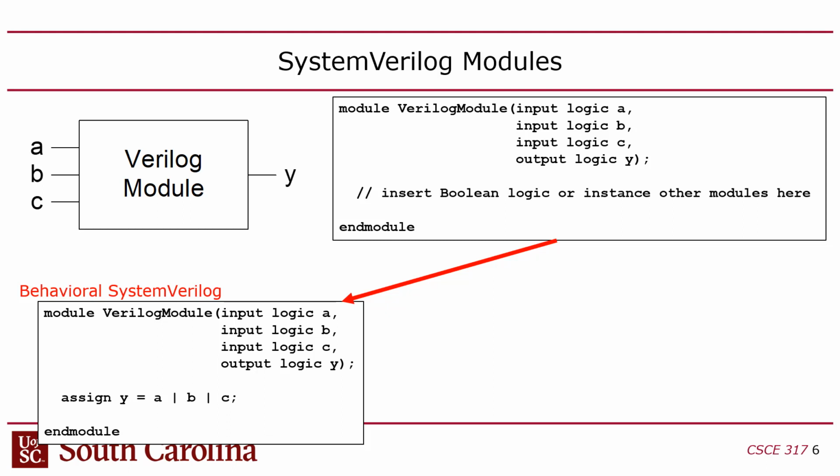But anyway, there's an assign, but then what's the other piece of behavioral logic that you can put in? You guys remember? The other language construct that implies behavioral? It's the always block, right? So there's the assign and always, and that's it. That's really the only behavioral code you can put in. Anything else is a schematic. Any other Verilog code that you write or read is either going to be an assign or an always, which are the leaf nodes, the very lowest level, right?